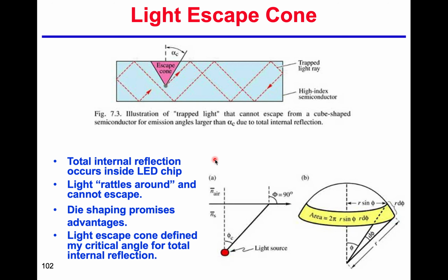Okay, so we said there are 3 factors that affect the efficiency of the LED: the current efficiency, light extraction efficiency, as well as the radiative recombination efficiency.